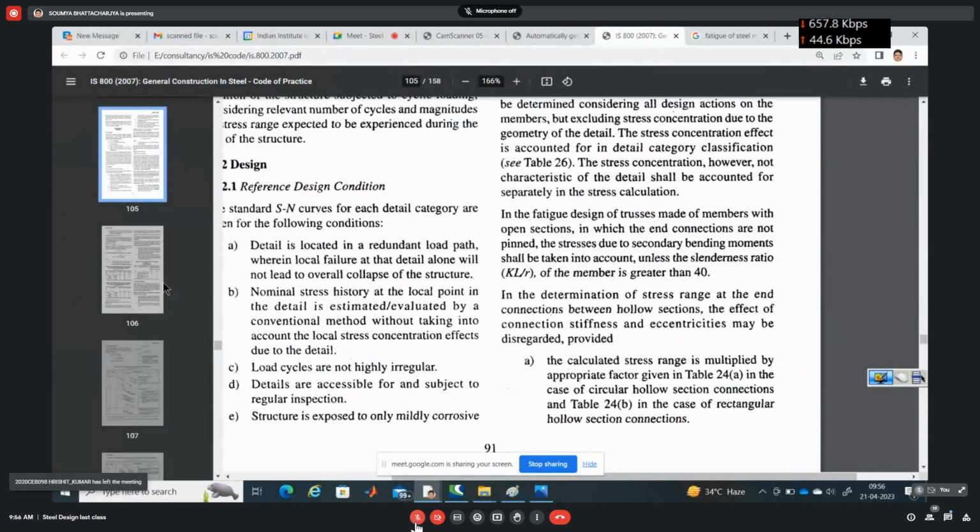It is not always 1.6, but for a gantry girder about the y-axis, you will see it is more or less close to 1.6. For this gantry girder type of section, about the y-axis, the shape factor is generally close to 1.6.